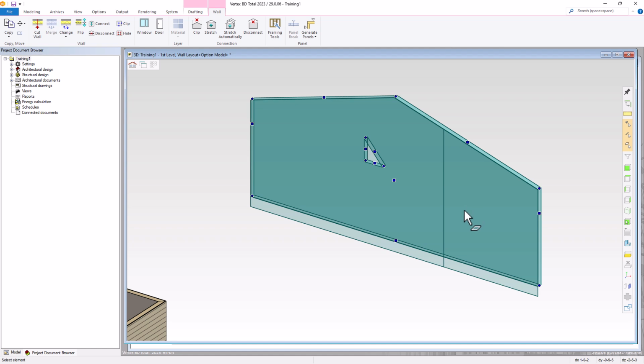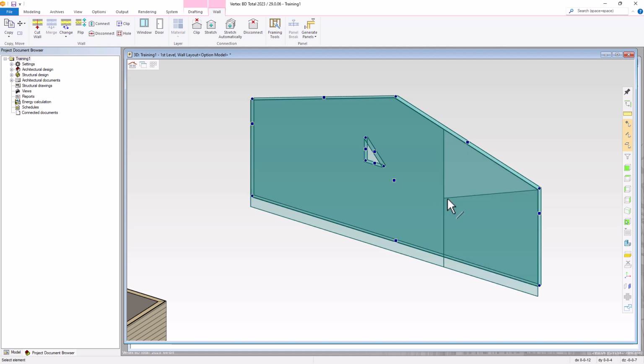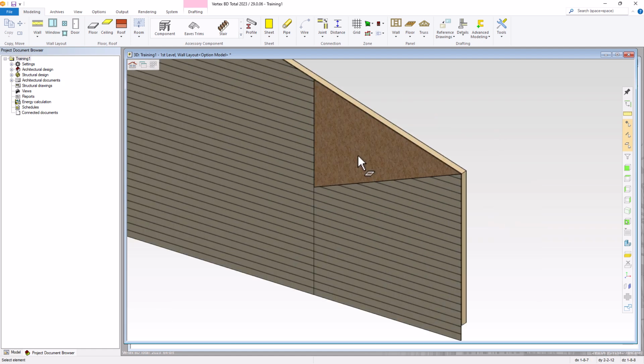Now we can select one of the split layers and edit that layer. Grab that grip point, lock it in the Z axis. Bring it down to, let's say, that midpoint. If I unselect, you can see now that we have the sheathing behind the siding layer exposed. Now the sheathing layer is still continuous. It has not been split. We only worked on the siding layer.